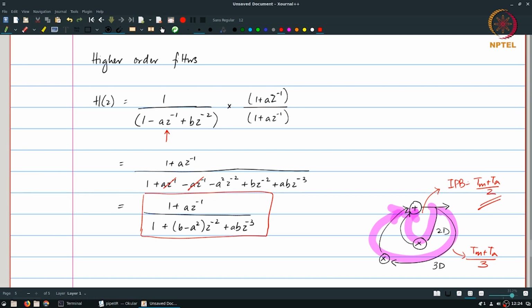Now if you implement it in a slightly different way, in terms of how the additions and multiplications are combined or placed one after the other, you might end up with a slightly different value for the iteration period bound, but that's just a question of how exactly you are ordering the different additions and multiplications. Once again, that's not really changing the algorithm in any significant way. The lookahead transformation is the one that has made a significant change to the algorithm as such.